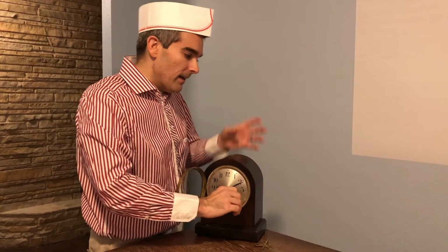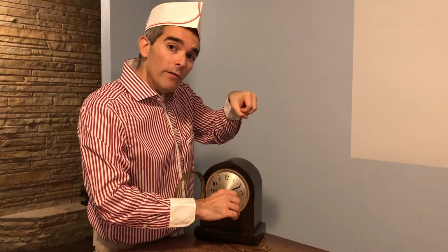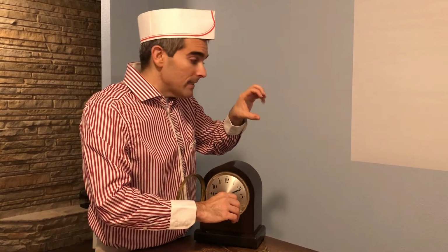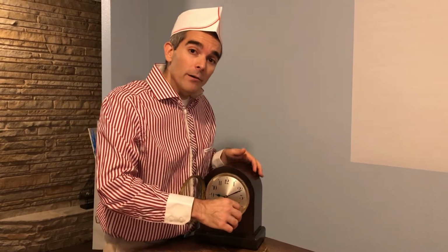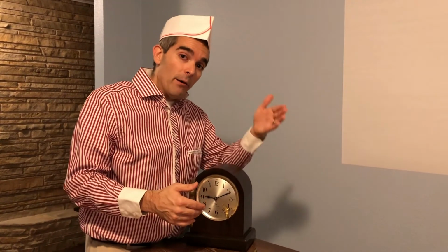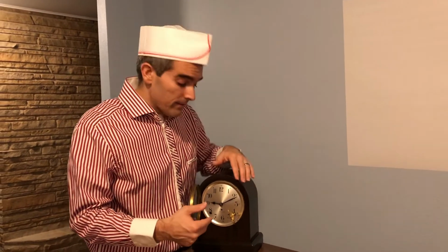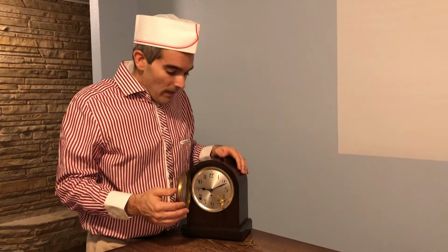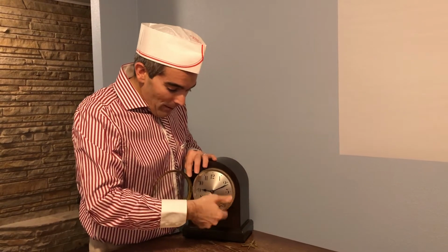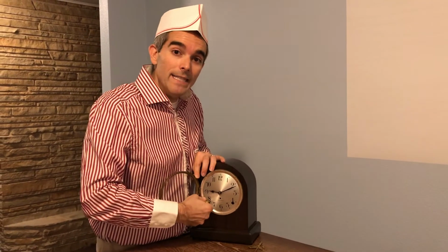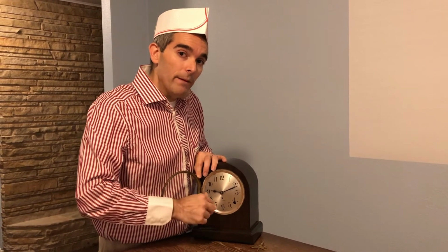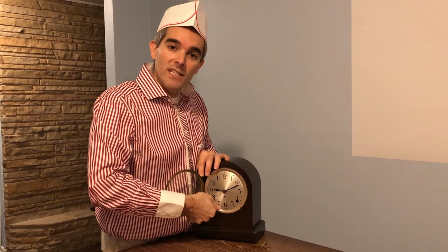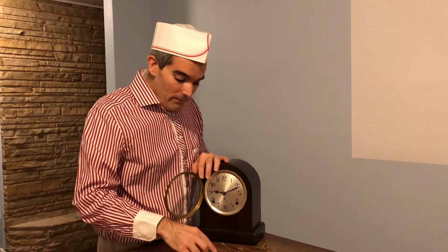This torsional spring will slowly bind up, and then over the entire 8 days it slowly releases, and that powers the gears, and then that causes the pendulum to rock back and forth, and that helps control how quickly the power is let down from the gears, from the springs, and then the clock runs. So it's pretty cool. This is how we power it. It's got two main springs, one powers the clock and one powers the chime. It's pretty interesting.